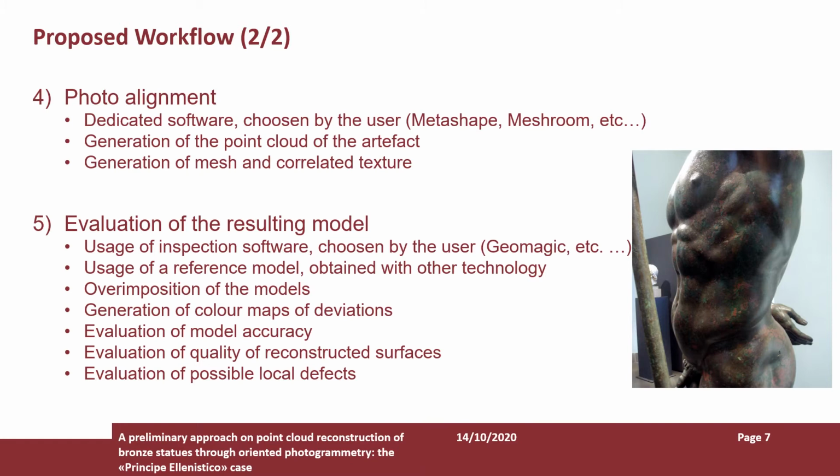It is always recommended to perform this comparison because of the huge variety of the artifacts in terms of shapes, geometries, and finishing. So the obtained model has to be overimposed to the reference one, generating color maps of the deviations. These make us able to evaluate the model accuracy, the quality of the reconstructed surfaces, and also the identification of possible local defects generated by the process.